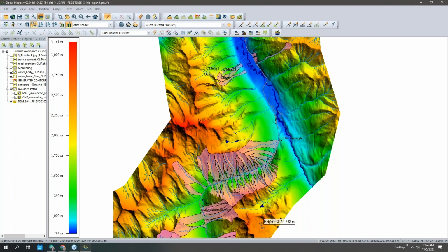So in order to show that in the 3D environment, we're going to create a 3D platform for that information to sit on and then bring that data in and give it a geospatial context. So that when we bring this into the augmented reality environment, we can actually see that reference data. So this might be a legend or metadata about your data, about the project that you want to add onto the bottom of your data set here.